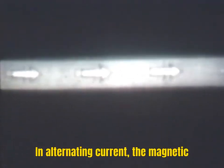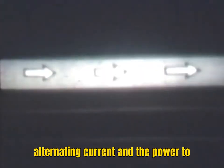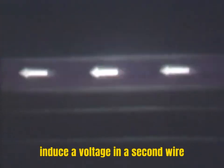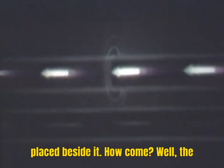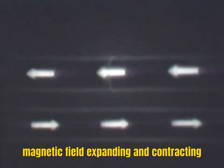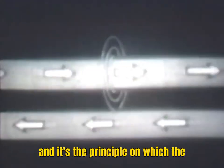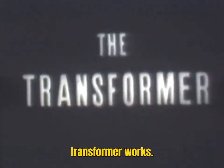In alternating current, the magnetic field expands and contracts every time the current changes direction. And now here comes the payoff. This phenomenon gives a wire carrying alternating current the power to induce a voltage in a second wire placed beside it. How come? Well, the second wire will pick up voltage from the wire carrying the current because the magnetic field expanding and contracting through the second wire induces this new voltage. This is called electromagnetic induction, and it's the principle on which the transformer works.